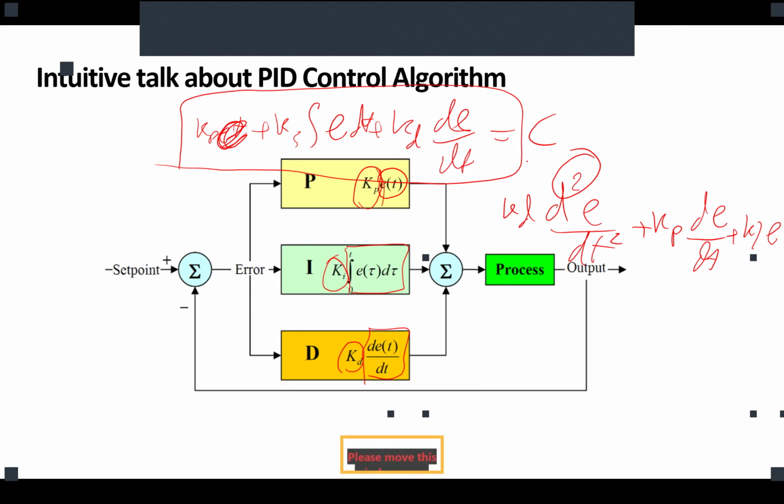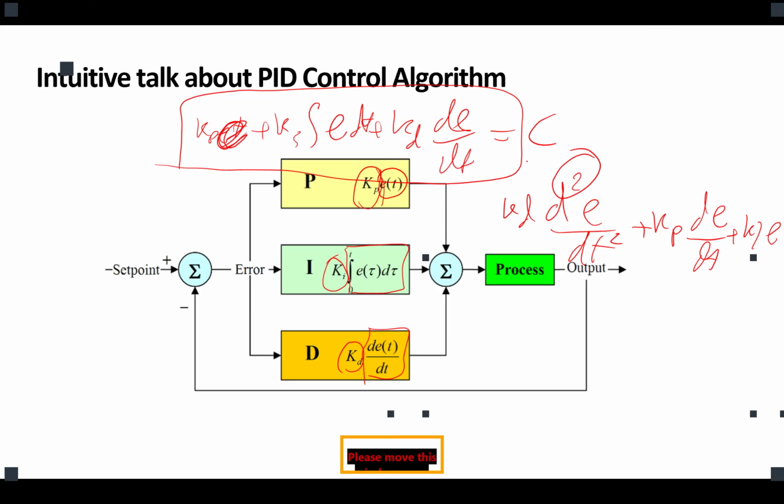It is a second order differential equation. What is the main aspect of second order systems? It has an oscillation, so oscillation would happen. You can eliminate that, damp that oscillation, but you have overshoot and undershoot no matter what you do. But you can manage to control that. Did you work with an RLC circuit before? Okay, so you've seen how you could damp the oscillation, or how you have a critical oscillation where the oscillation would not get damped and it's always there, something like that.